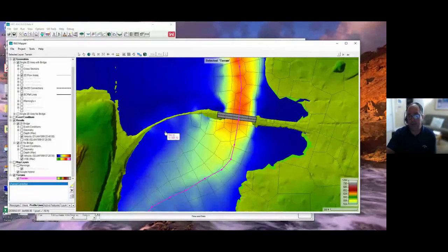Or if I still want to use a weir, like maybe this drop of water is too steep, and solving the 2D equations through a waterfall is not good. It's not going to calculate real accurate. But if I make this a separate structure, then I can use a weir equation and put its own weir coefficient for the flow going over. So I like the option of handling the overflows separately from the bridge curves because I have more flexibility.